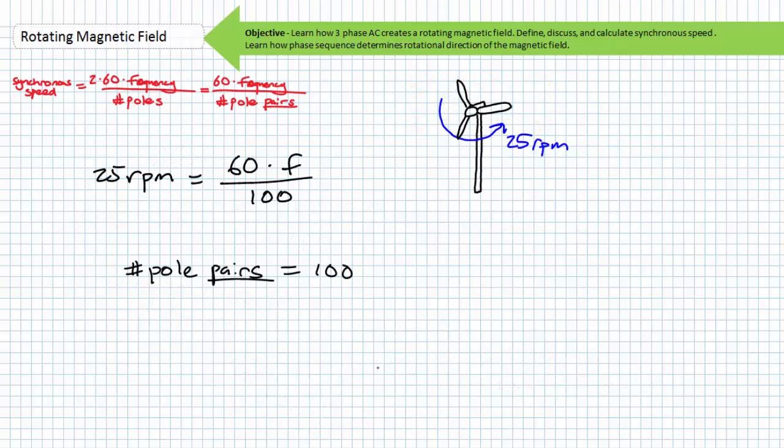Consider, however, a 100 pole pair per phase permanent magnet synchronous generator with no gearbox intermediary. In this case, if the rotor is driven at a relatively lazy 25 RPM, it would output 3-phase AC at approximately 41.6 Hz. Power electronics intermediaries can rectify this 3-phase wild AC output into pure DC and then invert it to grid-compliant AC with a proper phase sequence, magnitude, frequency, and phase shift.